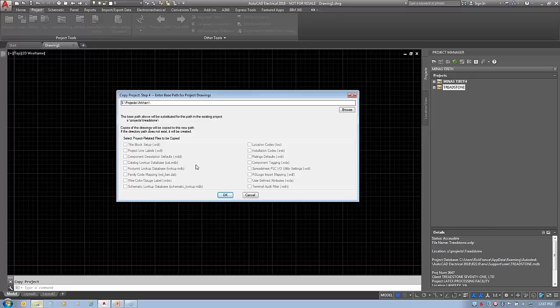The way I use the software is I use everything in a global setting. We'll talk about that in part 2. So I use one title block with a global setting, so I don't usually have custom files for a particular job. Sometimes I have clients who want that, and so I'll do it for that particular client. But normally, I'm using one title block. Everything's in my support folder, and so I may be using these files like the location and installation files I was showing you earlier, but they're global for all projects, not an individual project. And that's what this dialog box is dealing with.